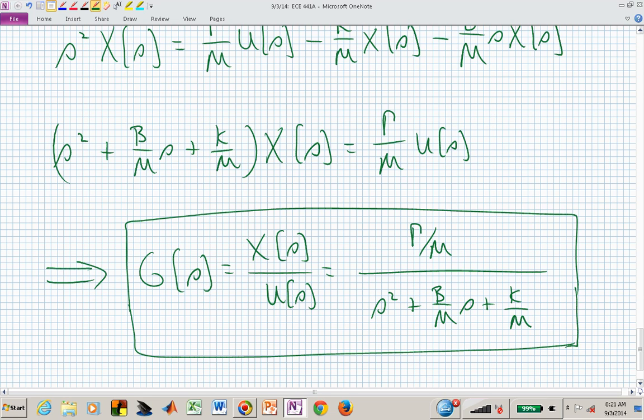I started with a block diagram representation. Are there questions about that process? It can get a little bit more tedious trying to chase your tail around some of those block diagrams, but if you try to look at the outputs of the summing junctions and then write everything in terms of what you need, which is usually the input and the output, then solve for the ratio at the very last step, you have your transfer function. Questions on that?